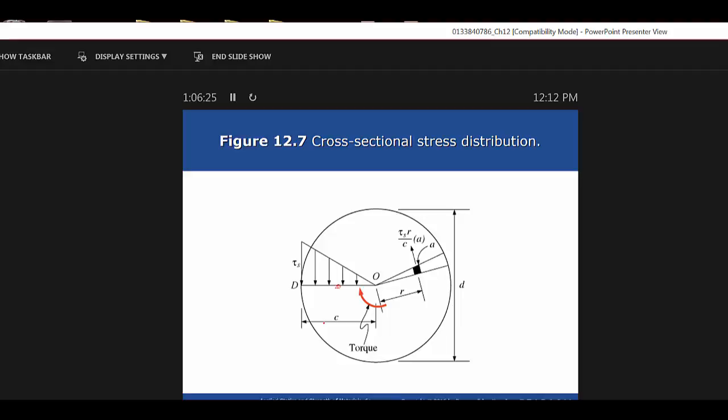Now the second part of that, you've got a hollow shaft and the outside diameter is 4, the inside diameter is 2. So again, polar moment of inertia, just take that outside number of 4 to the 4th power minus the 2, which is the inner diameter, to the 4th power, multiply that by pi, and then divide the whole thing by 32. Max shear stress is basically the same thing here. The only number that changes is the polar moment of inertia, because it's still a 4-inch diameter outside. The only way that number is going to change is if we said the diameter is 3 instead of 4. Then that 2 at the bottom would be 1.5, wouldn't it? That's the only thing there.